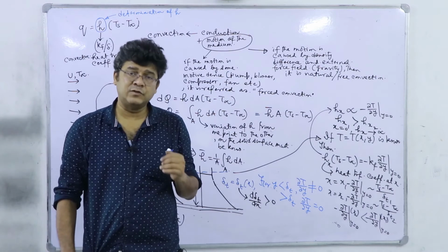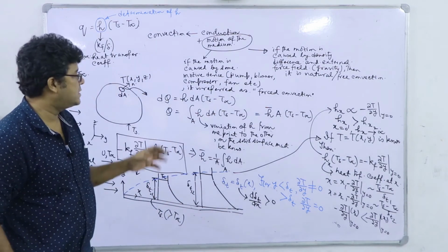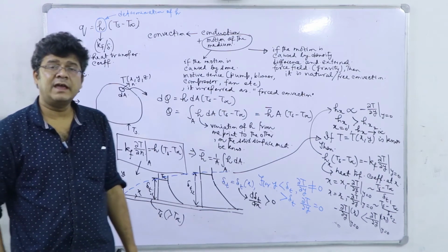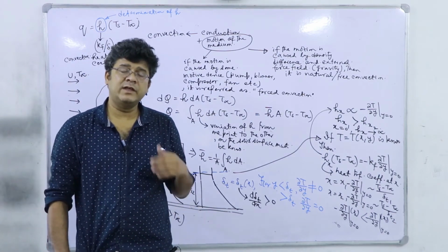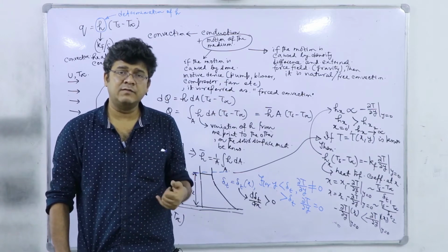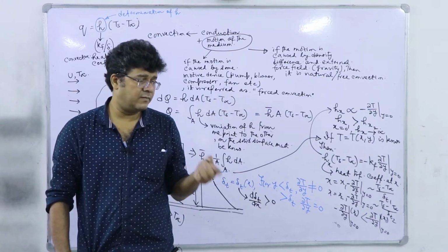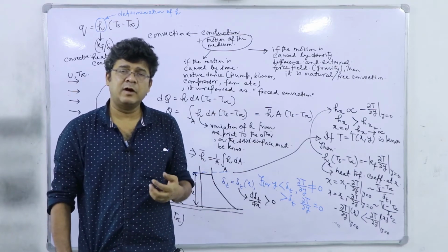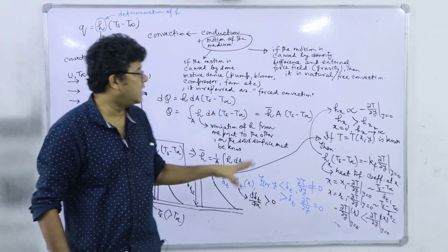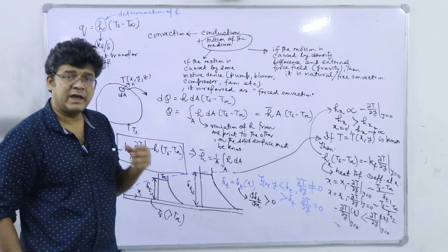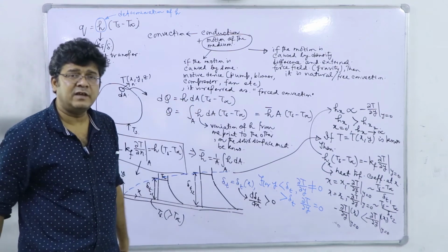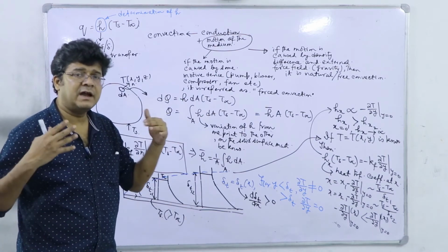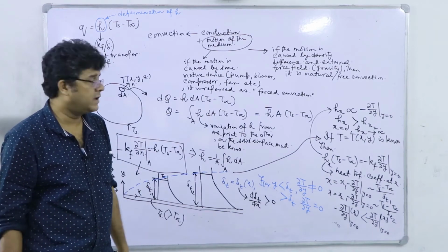So, if I have to solve for the temperature field, what will be my governing equation? Just like in fluid mechanics we have seen, whenever we are trying to solve this velocity field, we majorly used either shell balance, or in a generalized form there was the Navier-Stokes equation. So, here we must get some general energy equation, very similar to the Navier-Stokes equation, and solving that we should get this temperature field, right.